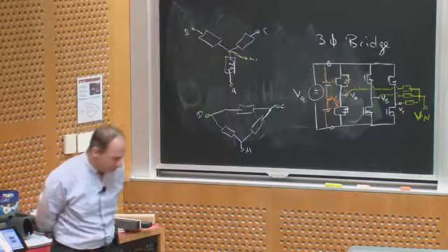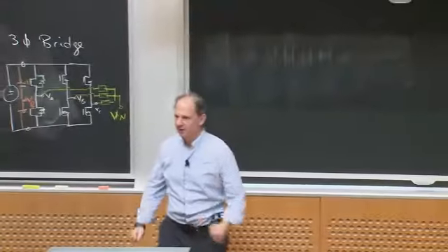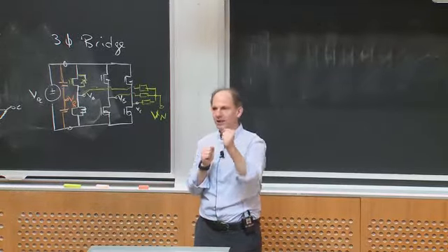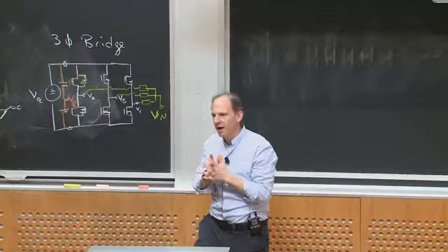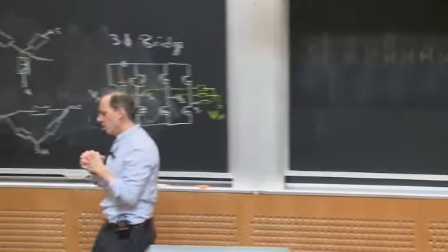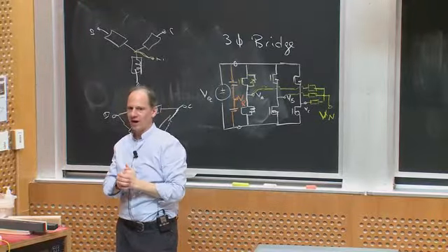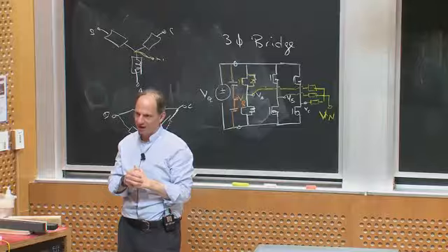Ah, that's a very good question, because if you think about a MOSFET's on state looks like a resistance, whereas an IGBT's on state looks like a constant drop. And it turns out that at the time that was built, for a very high voltage device, you could get lower forward drop for a given device area with an IGBT than you could with a FET.